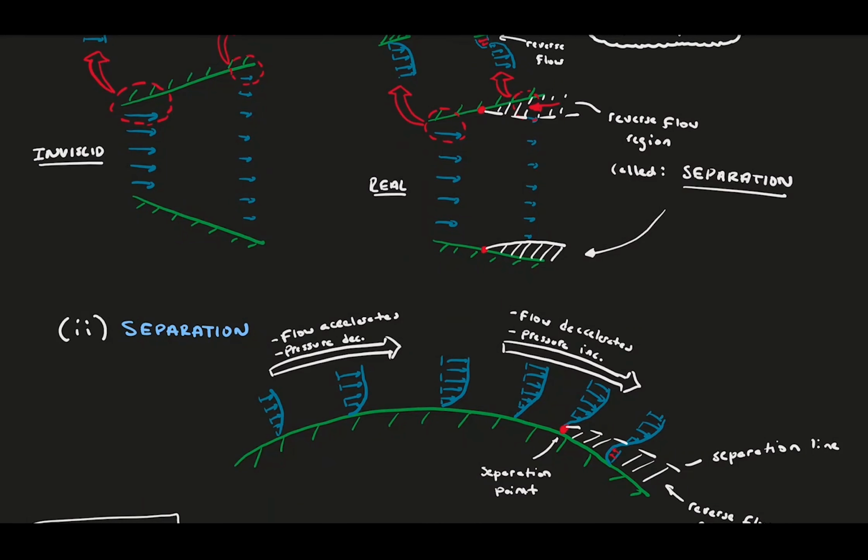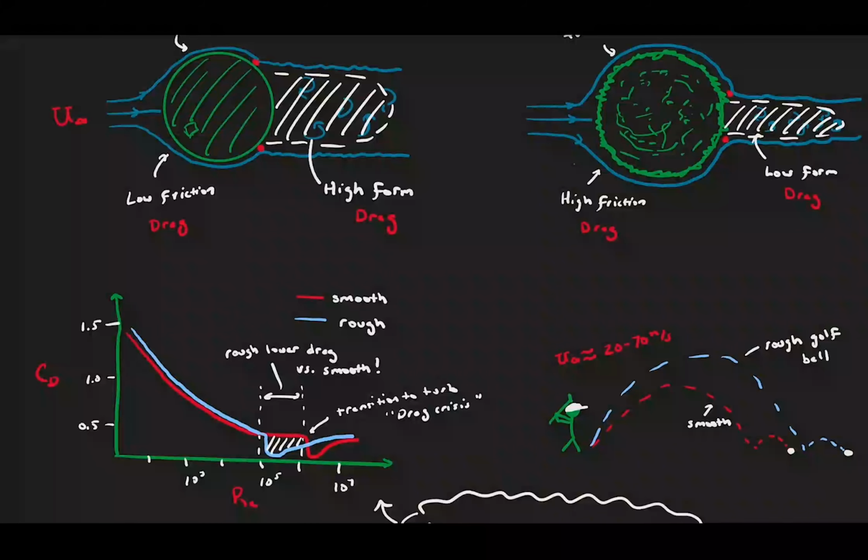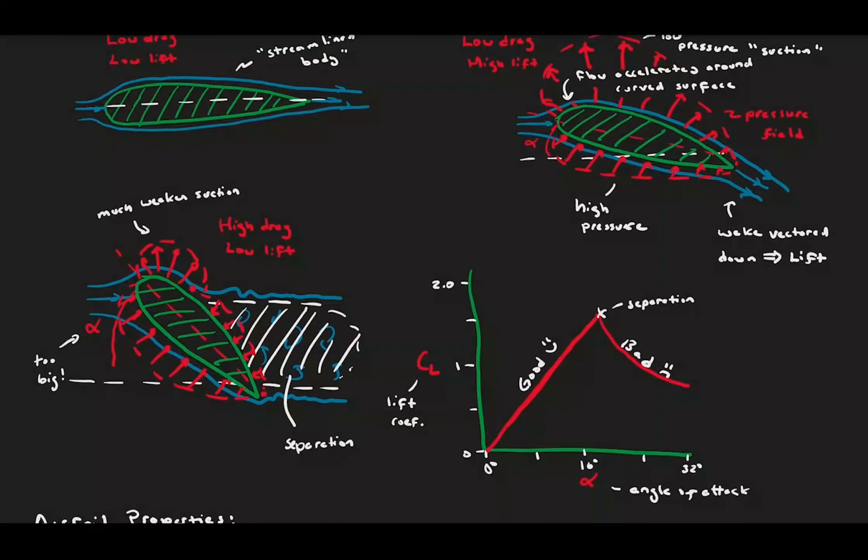If you include the boundary layer due to viscosity, this adverse pressure gradient produces separation, a region where the flow is either stagnated or reversing in the flow direction. This separated flow is detrimental to the lift forces produced and enhances the form drag on surfaces, which is generally undesired in application. We learned that although both laminar and turbulent flows separate, turbulent flows are much less likely to separate due to the higher velocity near the wall. Airfoils are specifically designed to avoid this separation and utilizing the pressure gradient to their advantage in creating high lift and low drag.